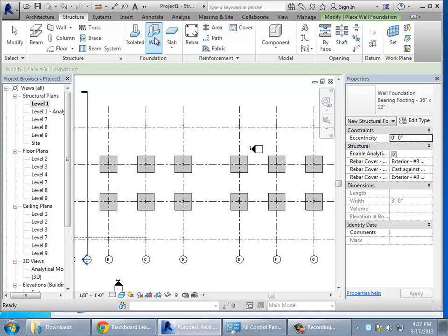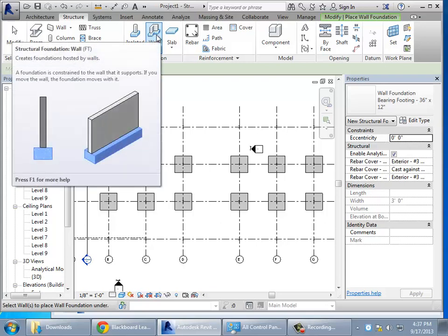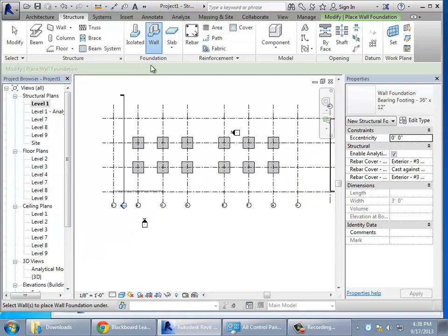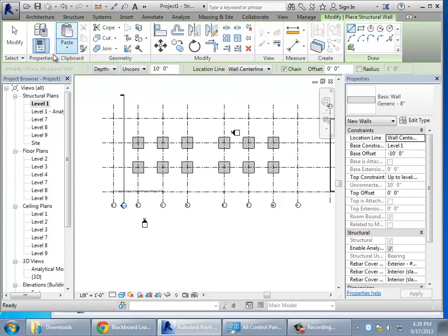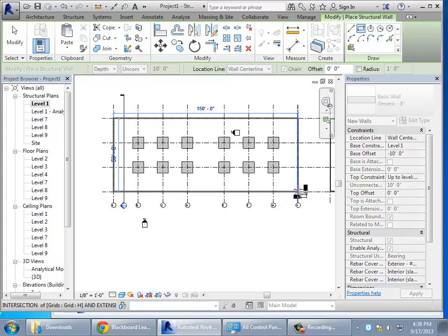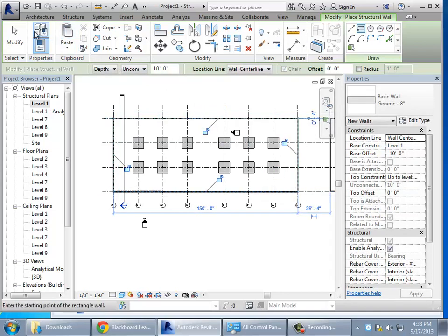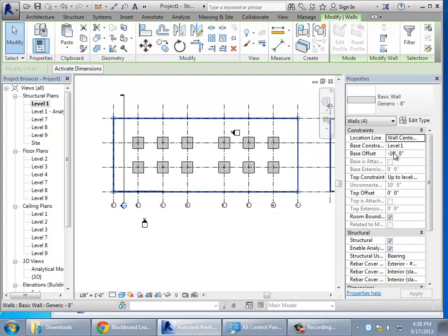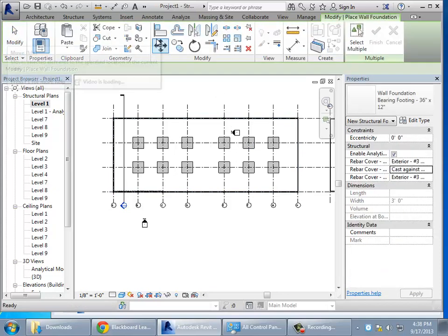I'm thinking about the right way to fake this in terms of what's going on, because it really is just a strip. But, oh no, you actually do have walls, because you have structural walls hanging around there. Okay. You have a wall foundation because there's actually a wall there. I'm trying to put a wall foundation under the columns, which doesn't make sense. Okay, there is some cohesion in life. What you really have going on for you guys, you have these structural walls, which are all around the outside boundary, going from level 1, 0 up to level 2, or whatever it is. You've got something like that going on. So if you have some nice structural walls around the outside, you can say the wall foundation.